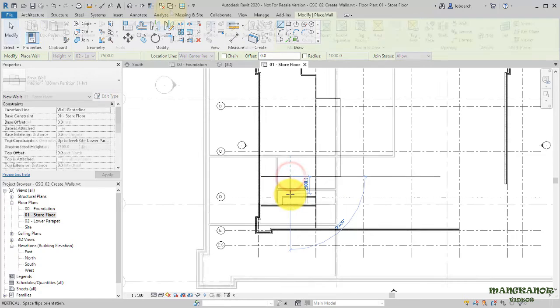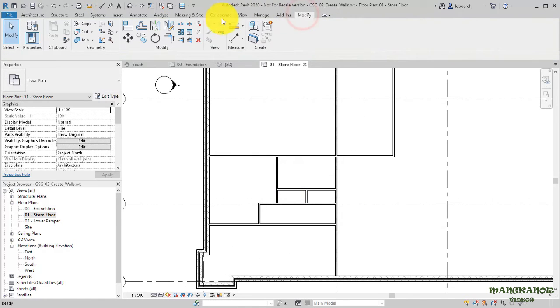While placing interior walls, you might find it useful to change the chain setting depending on the condition where you are placing walls. To create an opening for the hallway, you use the Split tool and split the wall into two separate segments at the point where the opening is needed. Next, you use the Trim tool, selecting the portions of the walls which are to be kept, thus cleaning up the opening for the hallway.